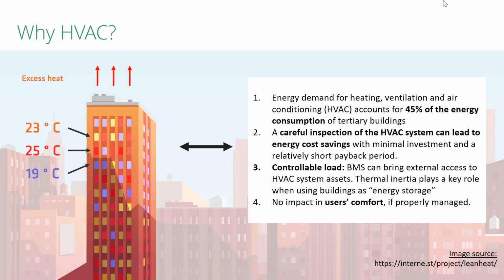Can you expand a little bit more about exactly how that's done? Yeah, well, maybe the best option to explain that is by means of the examples that we will see later on. But at the end of the day, when we are talking about thermal inertia, we are making the building behave as an energy storage because the walls, the floor, the air inside the building behave as a battery, and then we can temporarily stop or reduce the temperature set point so that we can shift the energy consumption from one point of the day to the other.